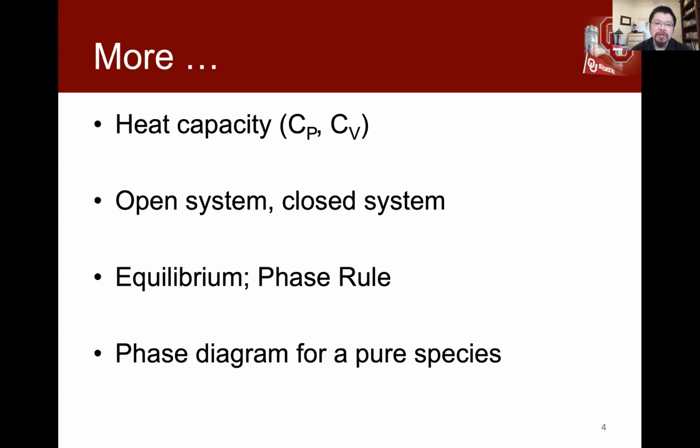We had a big chapter 4 on heat capacity. Especially, we tried to understand the heat capacity dependence on temperature. There's one function using coefficients, and we can express the heat capacity as a function of temperature. Also, when you look at Cp and Cv, I hope you still recall that for the ideal gas, we have a very nice equation to correlate Cp and Cv. So Cp is Cv plus the gas constant R, but that equation is only valid for the ideal gas.